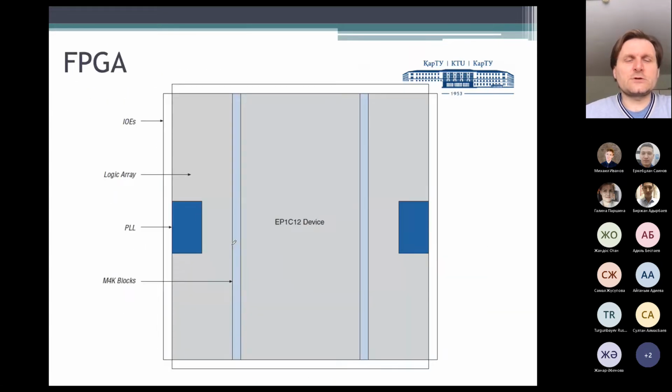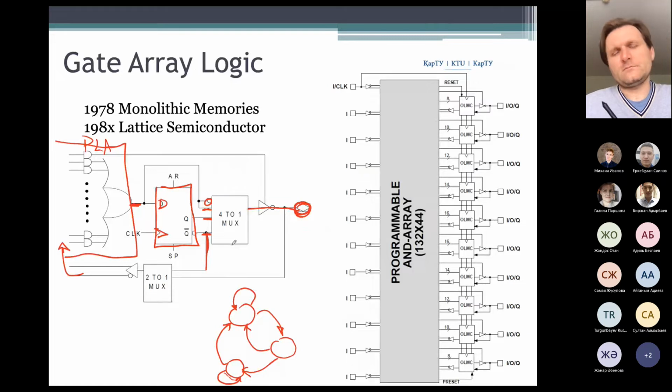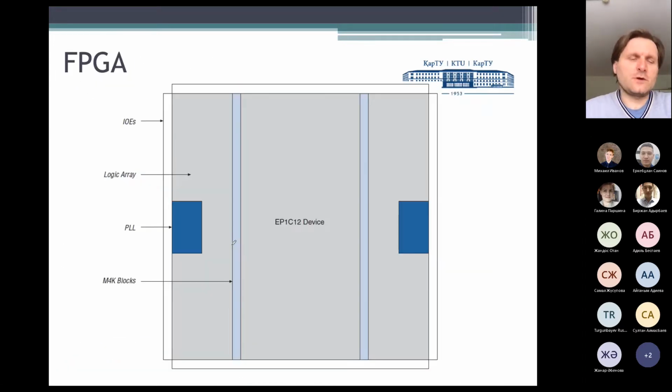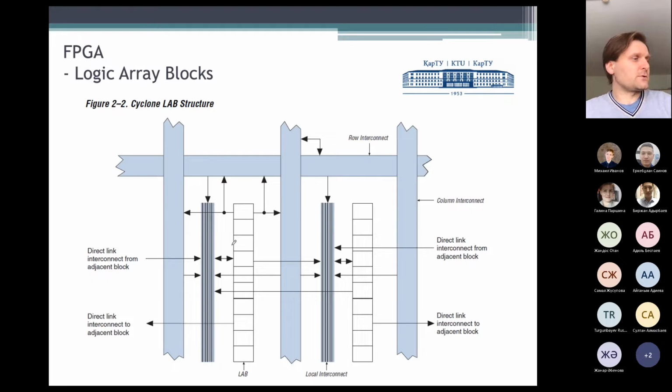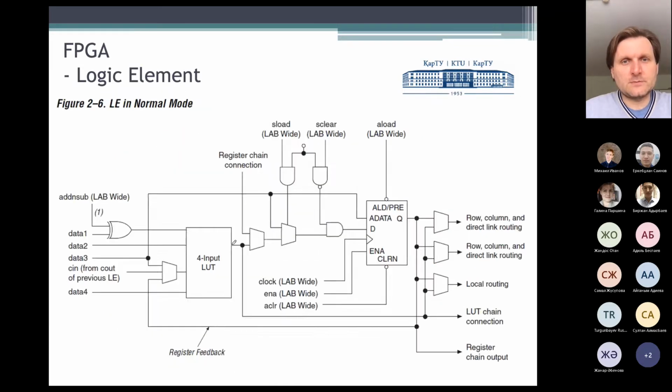So the FPGA structure is very huge and very hard to program, to predict, to obtain the structure directly based on digital behavior. For a structure like GAL, it was easy to build that system based on a set of gates, based on a lookup table. But for FPGA, where we have a lot of logic array blocks, we need special tools to manage that structure inside. I will show you that software in the normal lab, and I'll show you some examples.